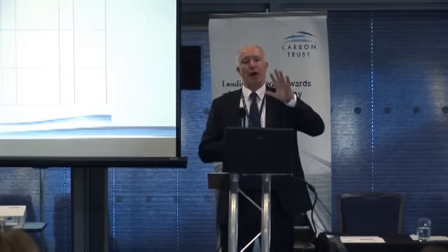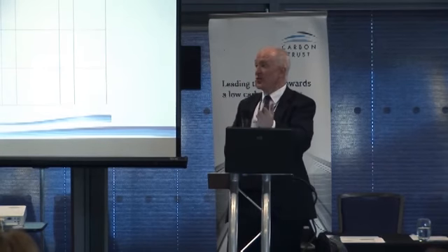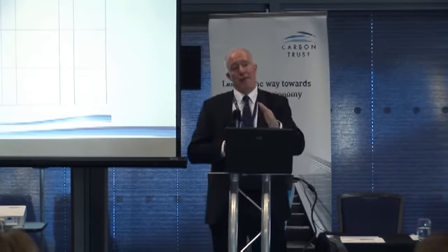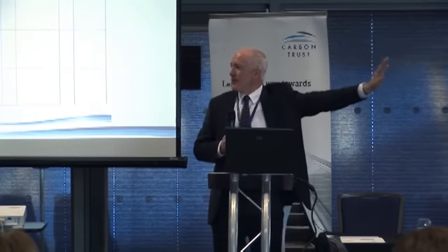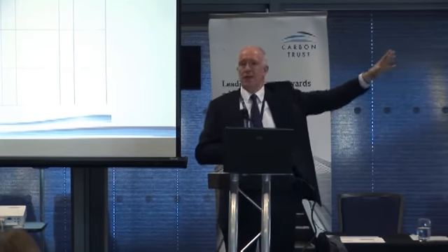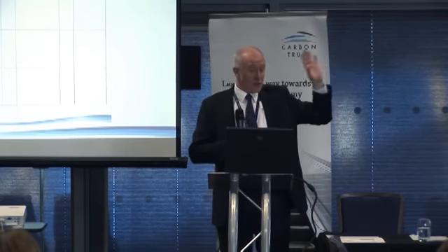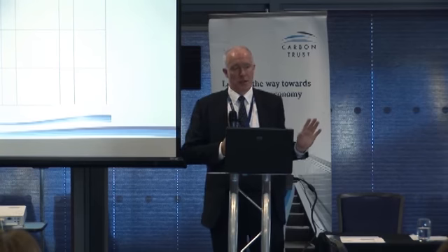So when we've got air coming out of our computer rooms at 30 degrees centigrade, or if we have air coming off the condensers outside rejecting the heat, maybe again at 30, maybe 35 degrees centigrade, that is a really useful, often continuous source of heat energy for us.